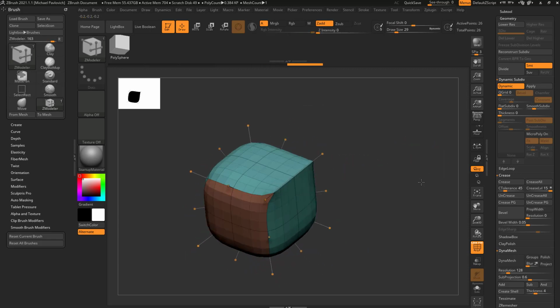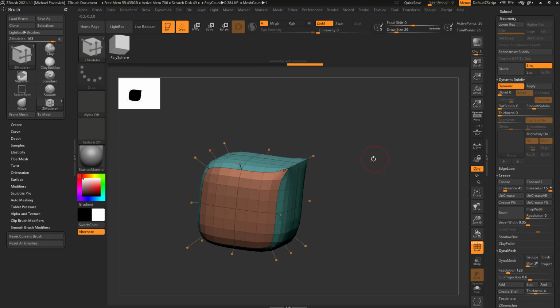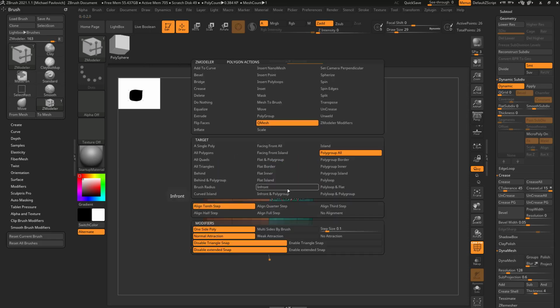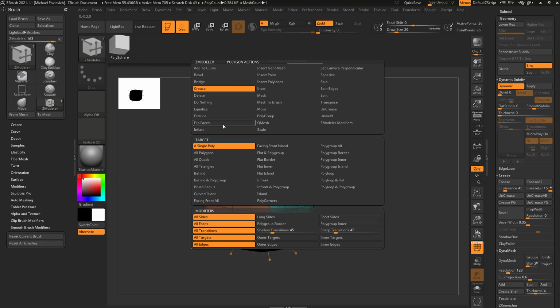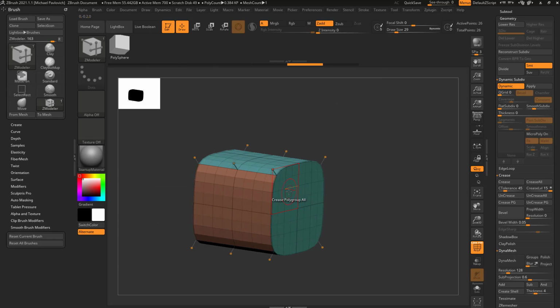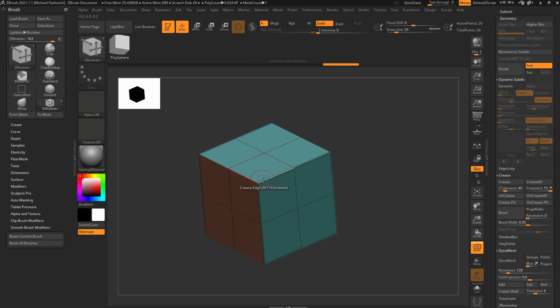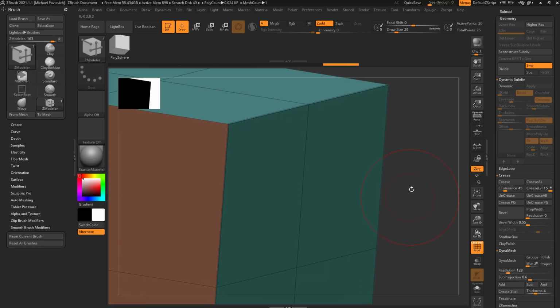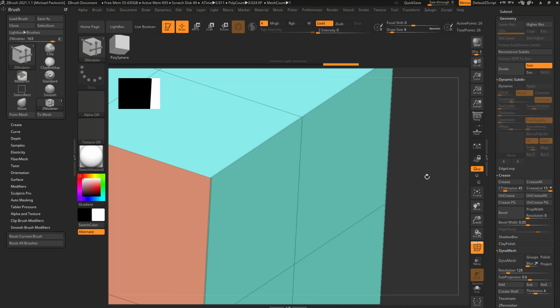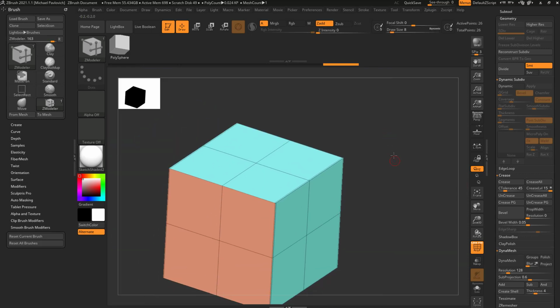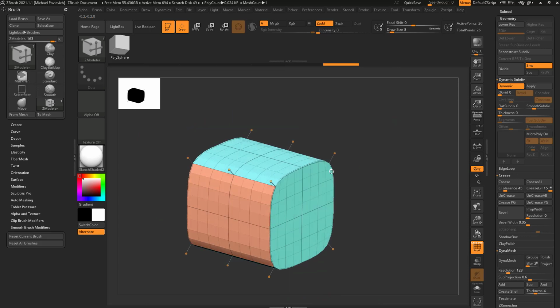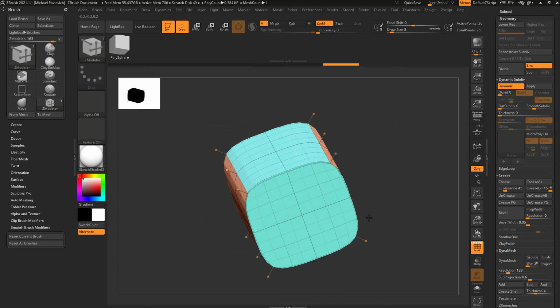You're going to see when we crease, it's going to hold that position a little bit better. In fact, you can hover over a face, and you can say Crease, Polygroup All, choose Outer Targets, All Edges, and then when I click on this, again, we have polygroups the same on both sides. So now it's going to take that entire polygroup border and crease it for me. If I do Shift D, you're going to see what it's doing is adding a creased line here. And if I zoom in a little bit and we change our material over here to Sketch Shaded 2, you're going to see there's a little dotted line there. Essentially what that's doing, if we hit D, is creasing that edge to maintain that edge.